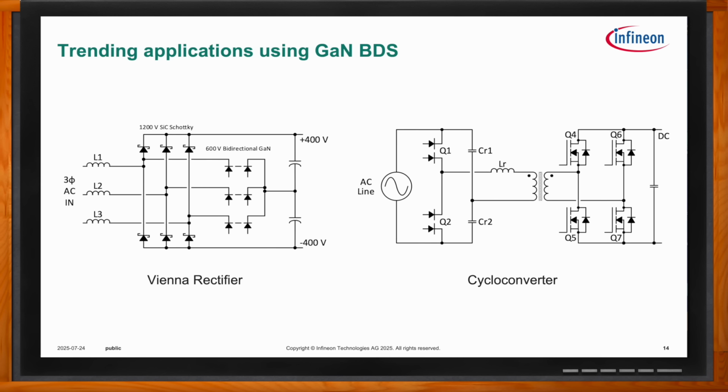With GaN, it doesn't have a traditional avalanche breakdown. It simply breaks down, but it's at a much higher voltage. For example, a 600 or 650 volt rated GaN device wouldn't break down until 1100 or 1200 volts. So they're actually rated right on the data sheet. We say, yeah, that's a 650 volt rated device, but you can temporarily, momentarily, on a pulse duration, go up to 750 or even 850. You just have to make sure that the total time spent there over the lifetime of the device is short enough to not impact the total device reliability.